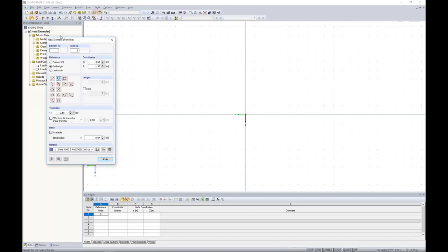So what we'll start off with is a new polyline. And with this polyline, I need to define the thickness of my cross section. So we'll set this to something fairly thin at 0.15 inches. Now, as I draw this polyline, I can also take into consideration a bend radius, and you can set that bend radius here. We'll choose 0.04. The material must also be specified.